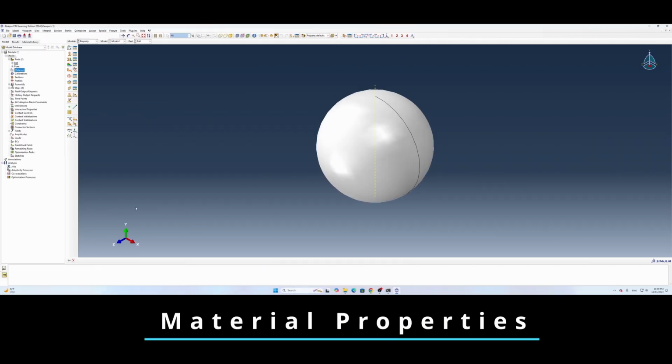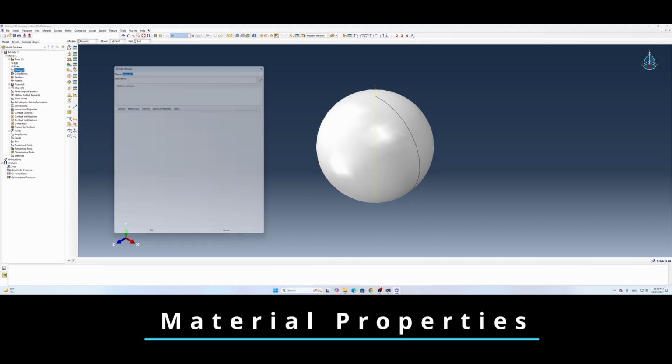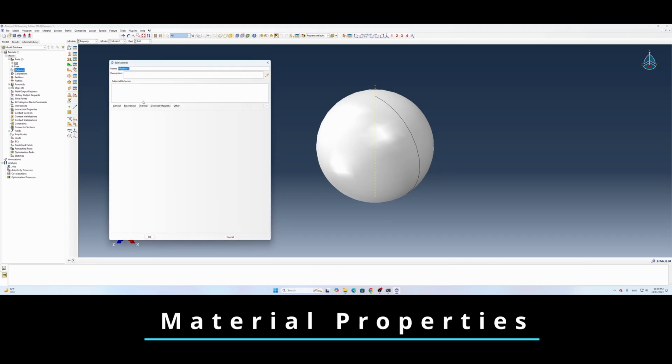And now we have to define the material properties for our parts. To do that, we go to our materials, double click, and then the name is going to be plate. And we define the mass density. In here, I'm going to use 0.1 grams per cubic millimeter, because the unit here is kilogram.